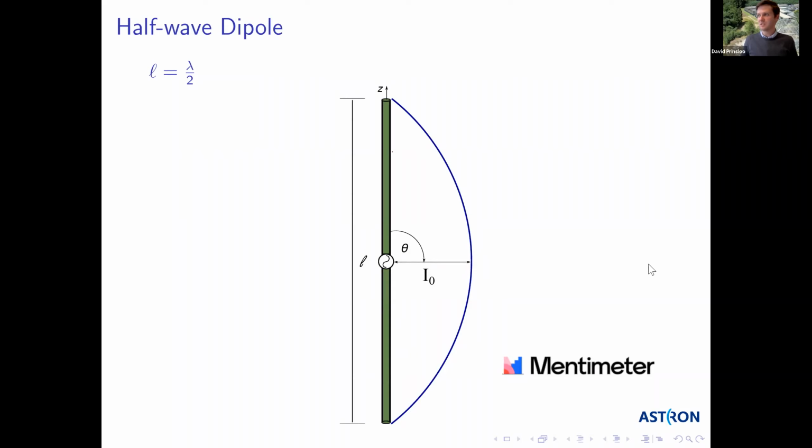So theta equals 90, indeed. But remember, this field oscillates around this point. So the maximum rotates continuously around the center. So you could imagine it oscillating as a standing wave around this dipole. So the maximum is always towards either 90 or theta equal to 270 degrees.